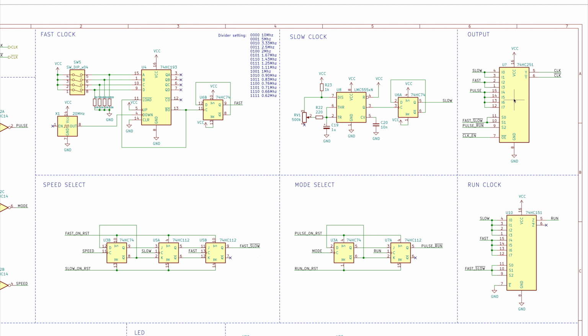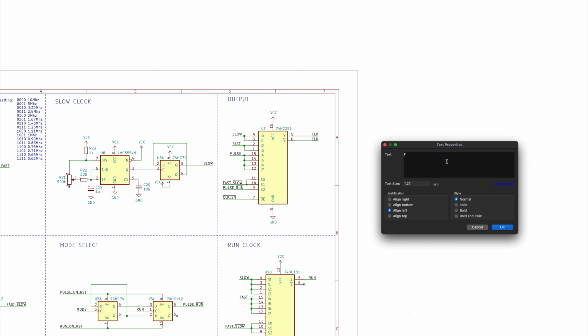So we want the switch to happen while the fast clock is low, because if the switch hasn't happened when the fast clock has a rising edge, it means that we have shortened the period of the fast clock, and that's not good because the fast clock is intended to be the maximum speed that the CPU can run at. So we don't want to shorten its cycle.